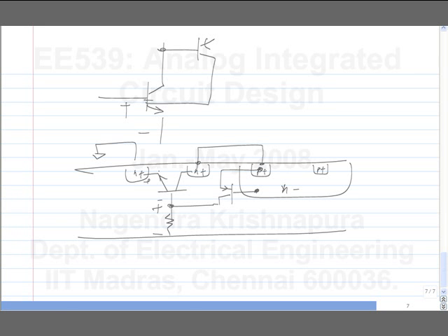Yeah, so right now the present way of isolating is not by just putting them all on a common substrate. There is some oxide between the NMOS and PMOS transistors. So the risk of latch-up is a lot smaller in modern technology anyway. So maybe it will be used.